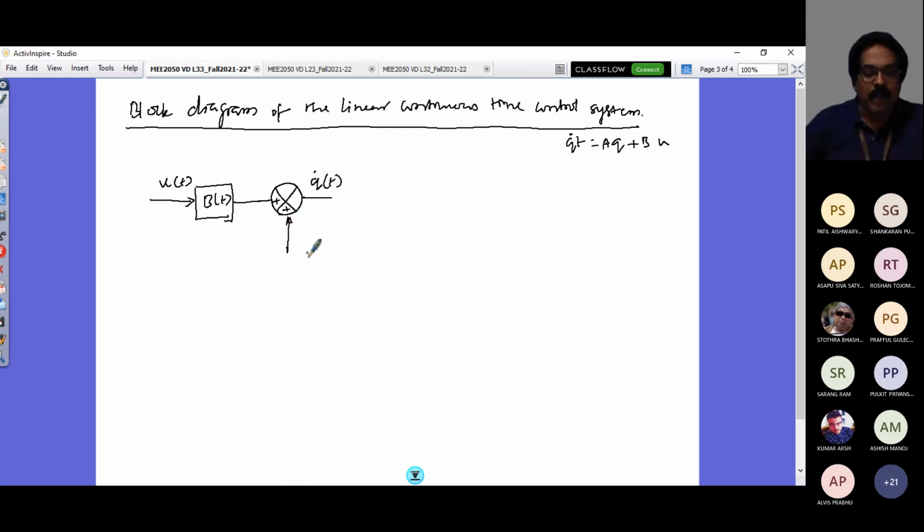So here I have to get parameter A of t. So it is time varying, representing that the parameters inside the A matrix also are a function of time. But in our bicycle model, you see they are not. For a steady state condition, they are constant parameters. So the A matrix would be a constant matrix, then it is a time invariant system.